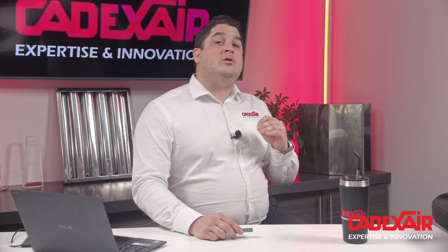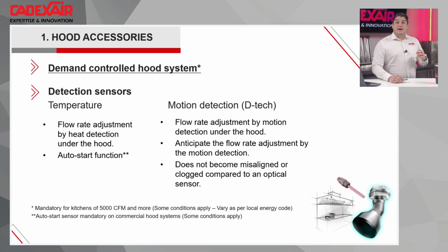When you have a demand control system, something important to have is a double detection. If you only have temperature sensors, it can be a little bit slow to react. So to have a double detection system with an optic sensor, in our case, we use what we call the detect sensor. It's really a motion sensor that, when you go under the hood, will react a little bit faster. And also why we created this: we work a lot with optic sensors on big systems, like a hospital with 200 feet of hood. When they open the combi oven, by the time the exhaust fan on the roof with a 20 HP motor accelerates, it's too late, the smoke is already gone.